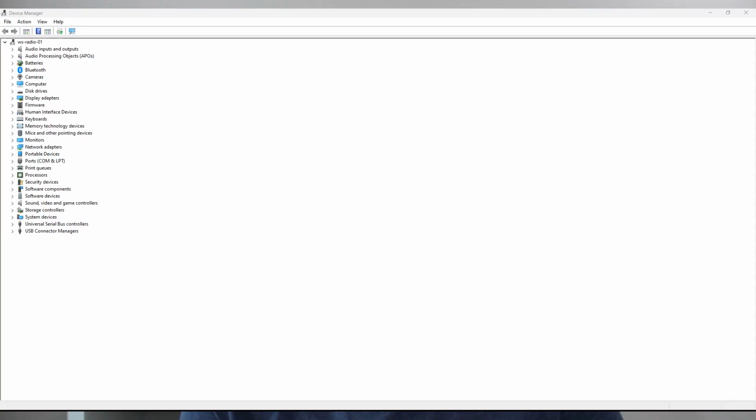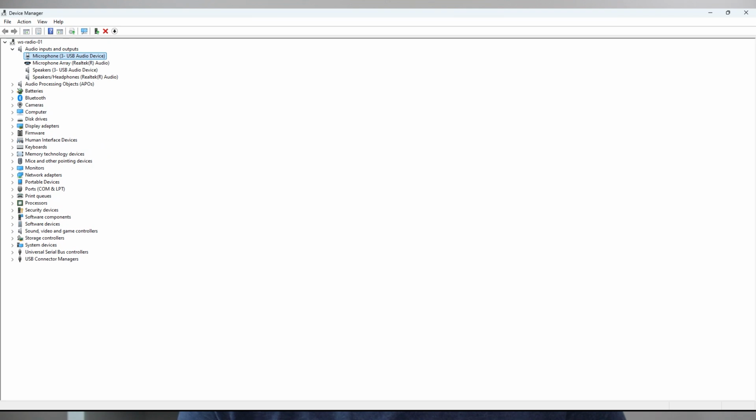The Digirig itself is a wired device that has a single USB connection to your computer, Raspberry Pi, or even your cell phone. From there, it hooks up to your audio's input and output. When you hook the Digirig up, your computer will see it as a USB audio device and a serial device. The serial device can be used for push-to-talk control, and it can also be used to program your radio with software like Chirp. When you're using the audio cable, your computer will receive the sound coming from the radio, and it'll be able to transmit sound to the radio.